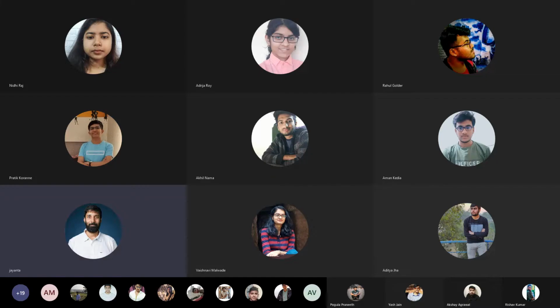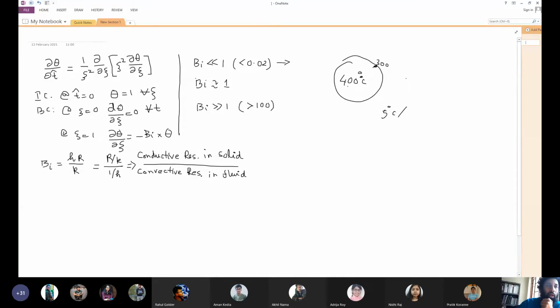The temperature of this is reducing 5 degrees centigrade per hour. Okay. So suppose it's inside a container or in a fluid which has very low thermal conductivity and very low heat transfer coefficient. So that kind of system we kept this copper ball. Because heat is removing very slowly, it has enough time to eliminate any gradient inside the sphere.